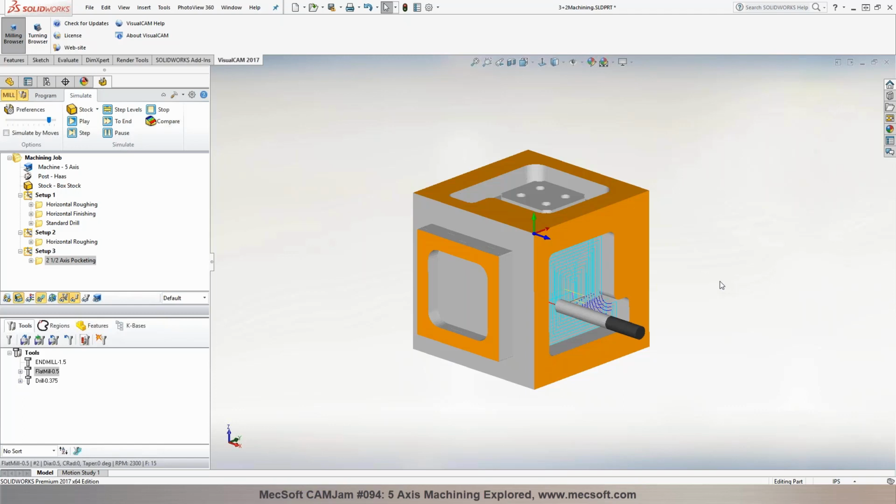Well, you need to have a planar surface if you want to use that for orienting your coordinate system. Now, if you have a sculpted surface, then you can rotate it by an angle, maybe like 45 degrees, so that the tool will be able to machine those features and there aren't any undercuts when looking from that orientation. Okay. My mouse is not helping to show you where, but no problem.